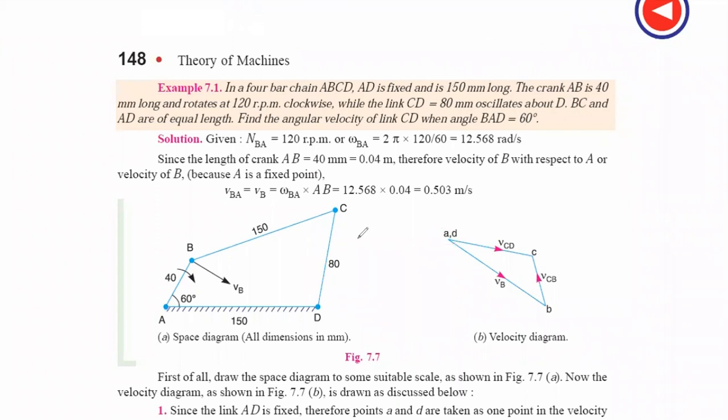Yes, sir. Now comes the velocity diagram process. You need to draw this VB. How to draw that, Anjali? Put your protractor over here. Suppose this line is going in this direction. Put your protractor in the rotating manner, with the protractor center lying over here. That 90 degree line is coming, Anjali, and that would be perpendicular to the link AB. So I'm telling you how to draw the 90-degree diagram.